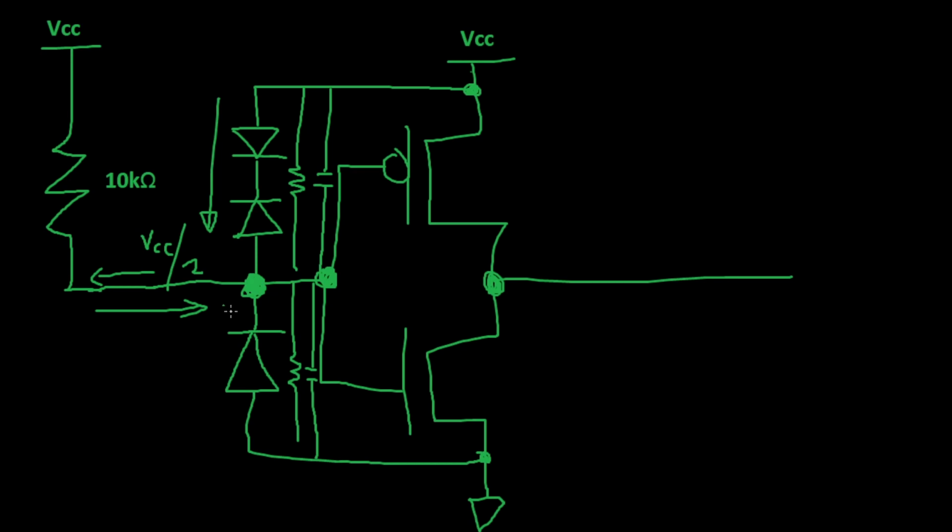Now, if you want to be able to model the resistance of one of these diodes, or all of the total leakage that's going on in here, because some current will go through the gates, some current will go through these, and some current may go through other structures that could be inside the device, we look at the maximum value that the datasheet lists, which is 10 microamps, and then we can just figure out how much voltage is going to drop across our resistor.